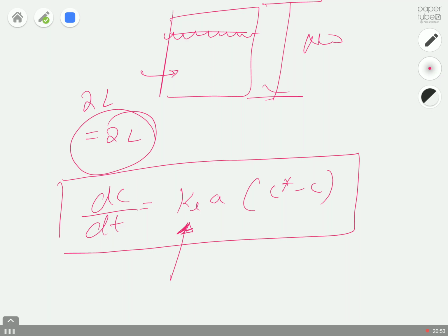Once the oxygen enters the reactor, it's going to get dissolved into the liquid, and then your microorganisms are going to uptake the oxygen straight away from the liquid, which means you are going to continuously lose some concentration of oxygen, because all the microorganisms inside the reactor are breathing. So you have to replace whatever oxygen you lost by consumption via breathing by the microorganisms. So that's why your mass transfer should be really high. And how to calculate that? For that you need this one single expression.